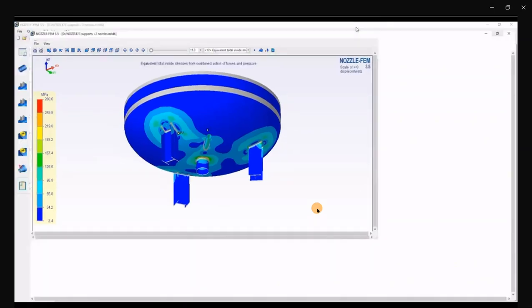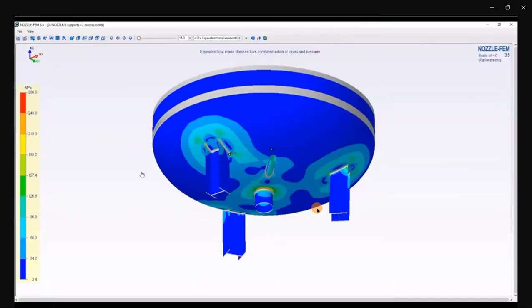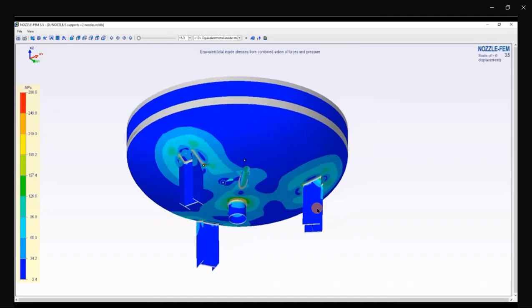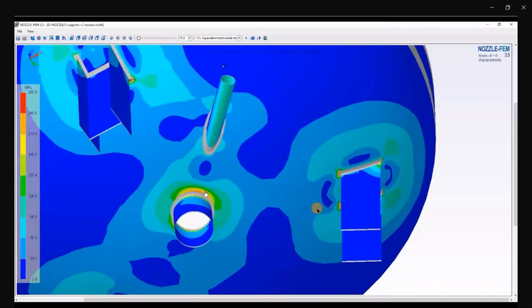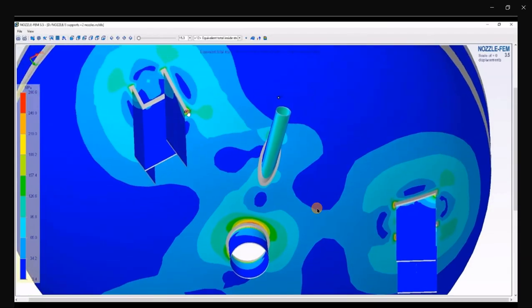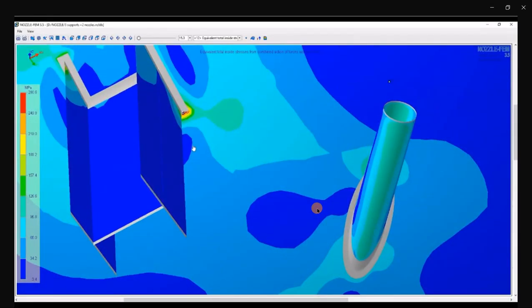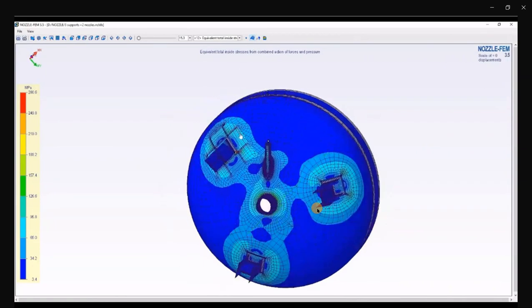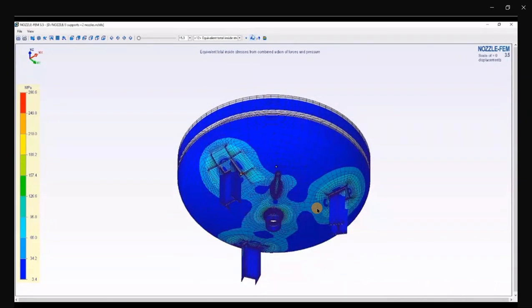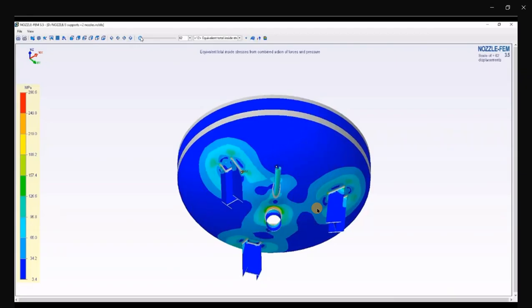post-processor, where we have a comprehensive instrument for detailed stress conditions, not only stress conditions. We can see that maximum stress in this case is in the bottom shell near support. Click with grid elements, without grid elements, deformation, yes.